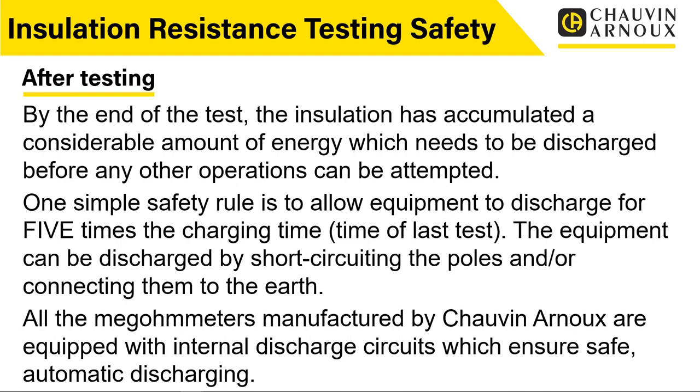When we actually charge up insulation, depending on the capacitance, it's like charging up a big capacitor. So if we've tested at 1000 volts, we've charged that up to 1000 volts, and that's going to sit there. Now, potentially, if we don't discharge it, we come along, we touch those cables, that's going to discharge through us. So we can still have a shock. Even though the test meter's been disconnected, the test meter's been put away, we've stopped pressing the test button, we could still get a shock off that. So it is important to make sure it's discharged.